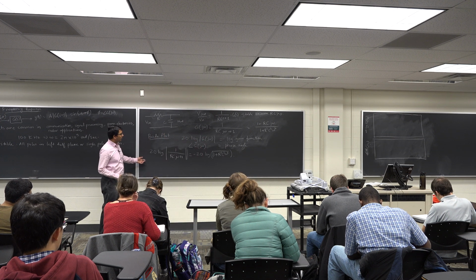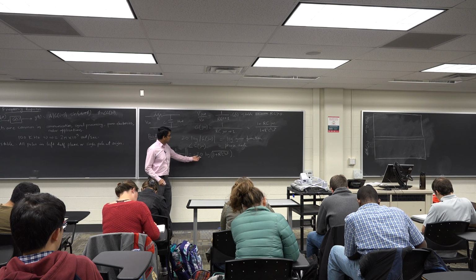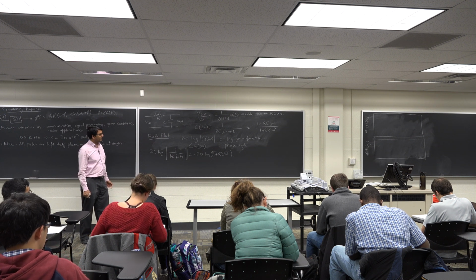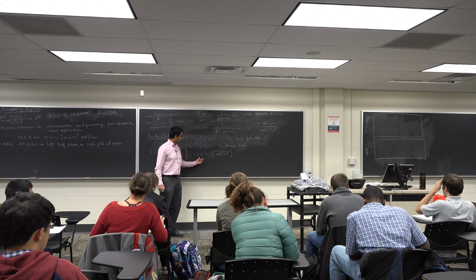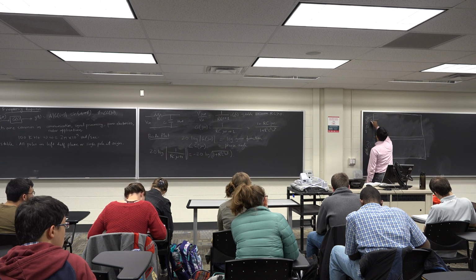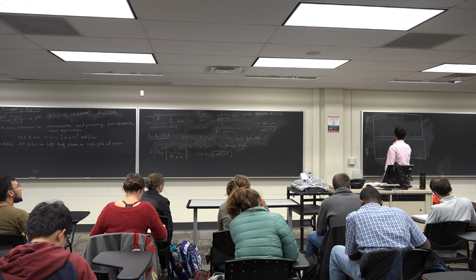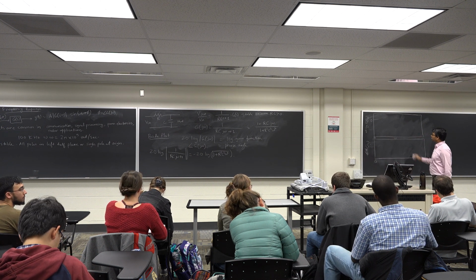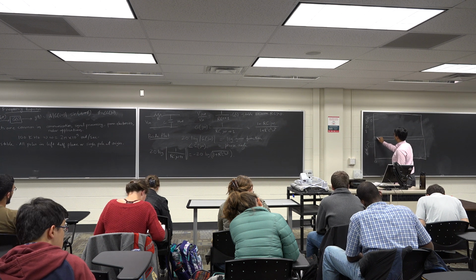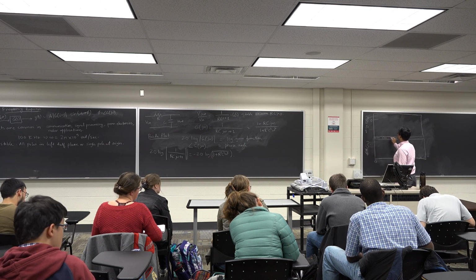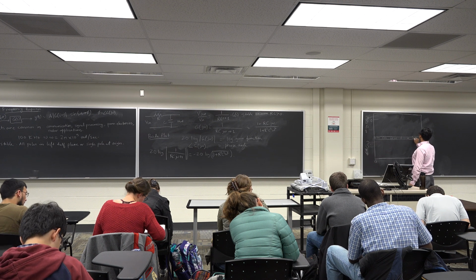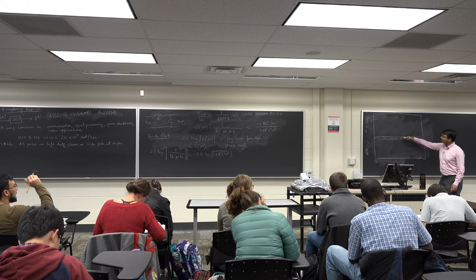Okay. So what happens when omega is very, very small? What happens to this number? What's the log gain at omega close to 0? Yeah, so this will be log 1, and log 1 is 0, so you actually have 0 log gain at omega equals 0. And usually this x-axis is in the log scale, log base 10 scale. So you have 0.001, 0.01, 0.1, 1, and then 10, 100, and so on. So this x-axis is in the log scale.